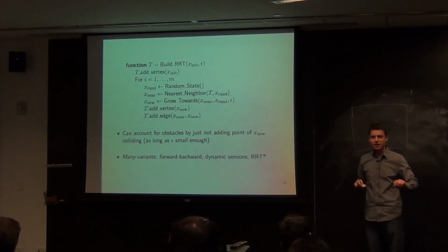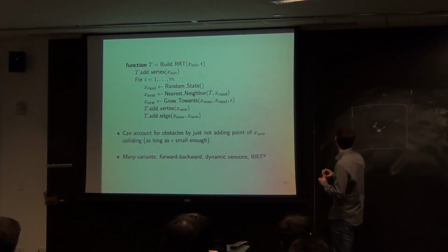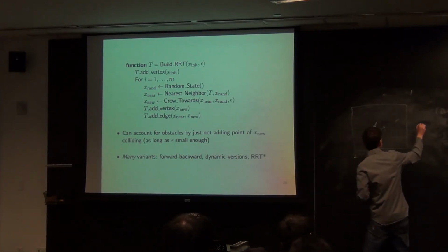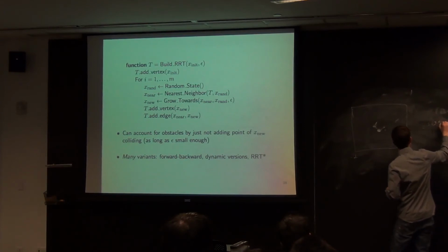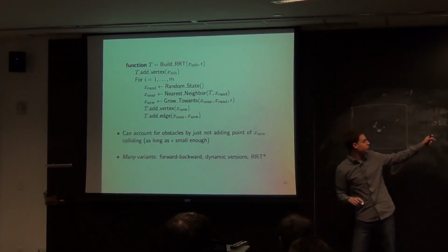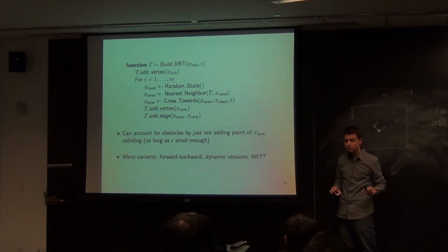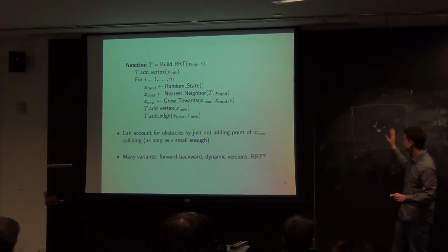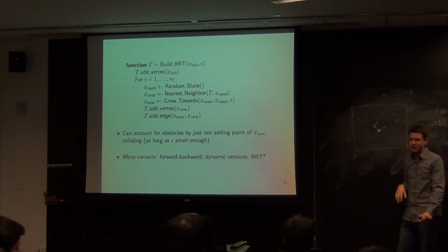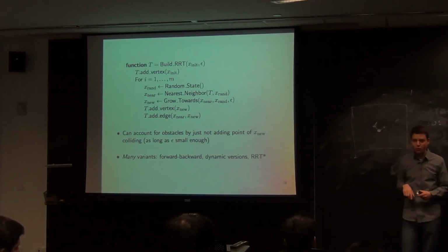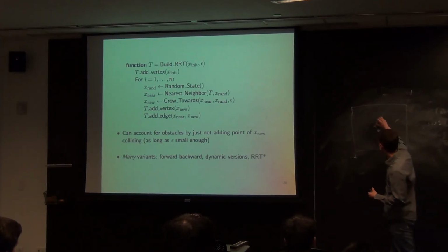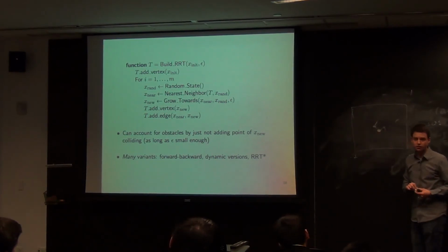Now, if we sample a point that's actually within epsilon of our existing points, epsilon here isn't like machine precision. Epsilon here is like, you know, if this is like 1 and -1, a reasonable epsilon would be like 0.1. Something small enough, and actually that has to do with the size of obstacles in the space too. But don't worry about that. It's something small, but not that small. If we're actually within epsilon of the point we sampled, then we just connect it, period. So if this is our point we sampled, then we'll just connect it exactly. But otherwise, we just keep growing in this process.